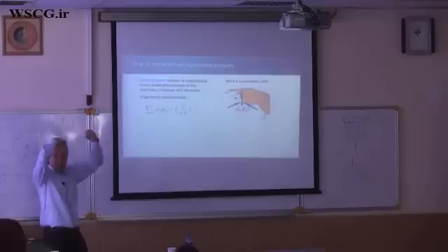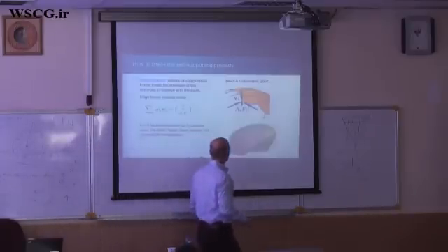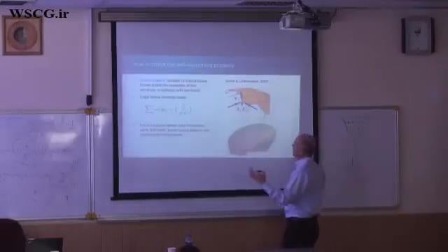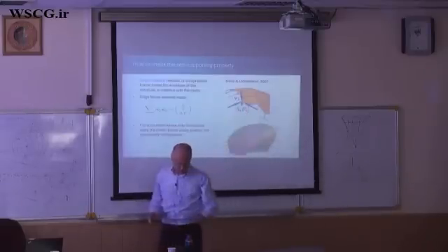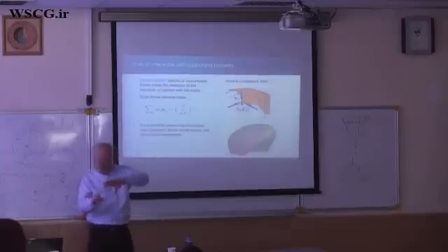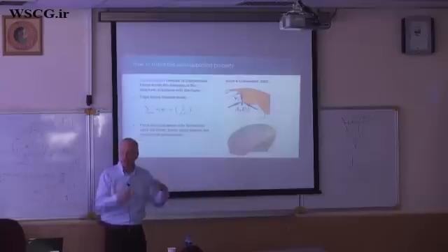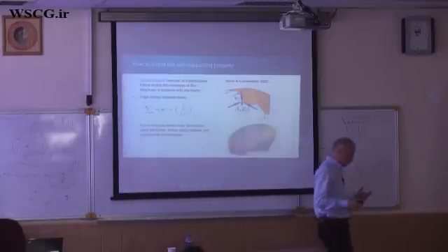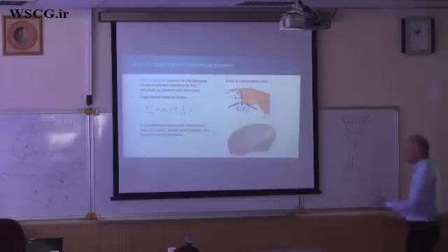When this load gets too big, there will be no thrust line inside the hull, and then it will fall down. And of course, it depends where we place these forces. In a general masonry structure like I had before, these edges just need to be inside the masonry. There are no preferred directions. If we have a steel glass structure and we do not want to have any forces in the glass, we must have our thrust network within the steel beams, obviously. So then we are more restricted.